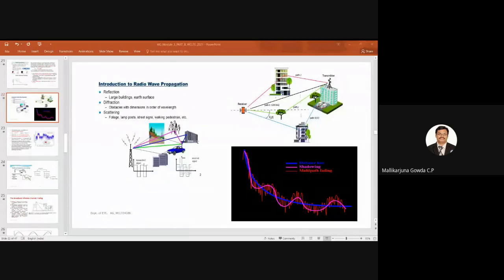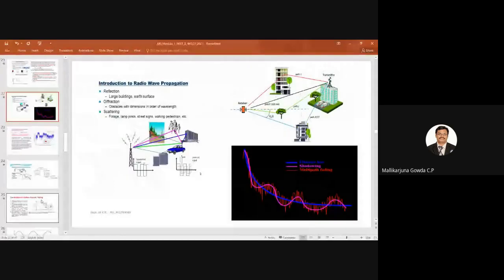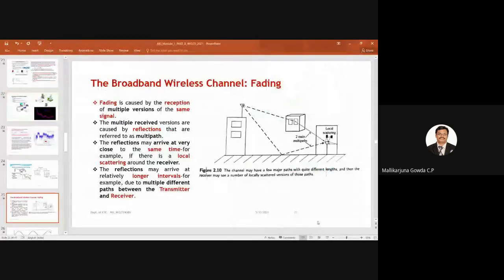So this, as I said, is because of these things. Since the channel is wireless and it takes multiple paths, depending upon the distance, I will be receiving the same signal multiple times, right, with a different magnitude as well as at different times. Fine. So that, I said, is known as fading.